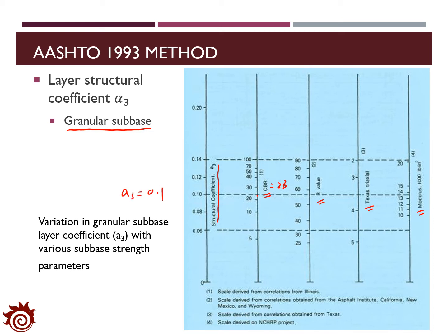You can also find out the value of R or the resilient modulus and use them to determine the value of the structural coefficient A3 for the granular subbase.